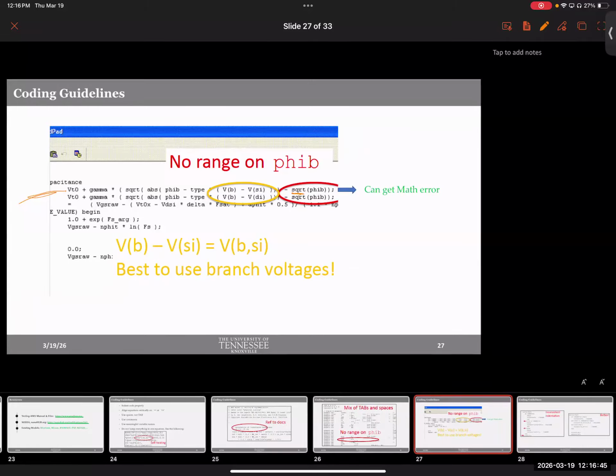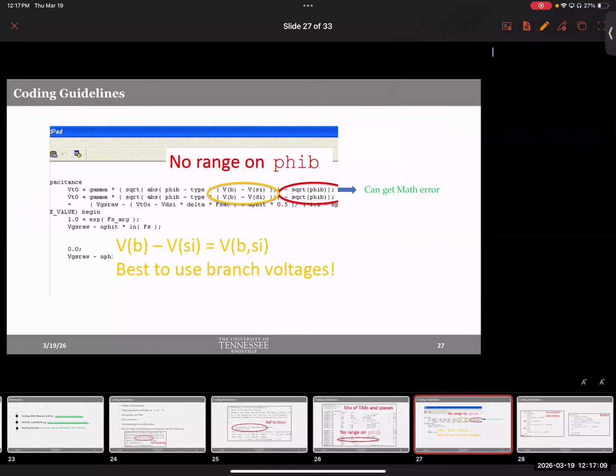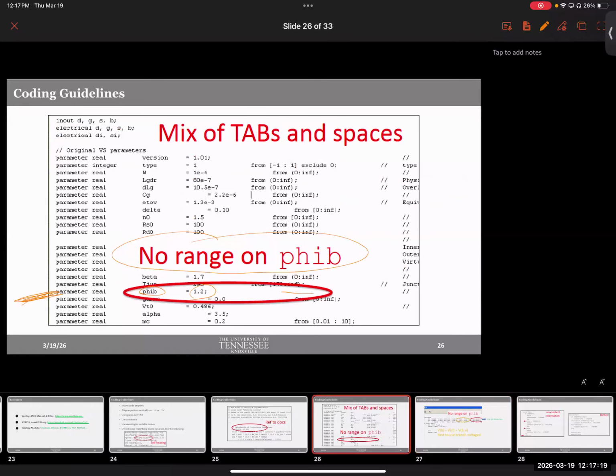By the way, that's the other thing. Verilog-A gives you these functions, log, like ln, basically. It gives you functions like square root, which you can easily use, like MATLAB, for example. So this is a square root function. Within the square root, you have 5b. I don't have to tell you, if you have square root of -2, it's going to be a problem in your simulation, don't you think? It will give you an imaginary number. So, of course, you got it. How can you make sure that you don't get a math error here? How do you ensure that?